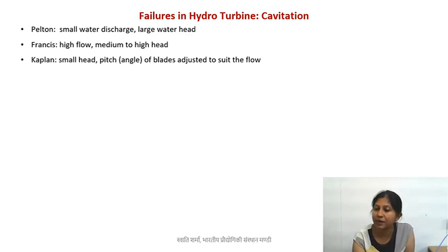The fluid is completely different. Not just that the fluid is different, one more thing is that the wind velocities can be very different at different time points. You know, sometimes you can have very turbulent winds, sometimes you can have no winds at all. But in the case of hydro turbine, you're pretty much controlling the flow rate of water. So that is one difference. Another difference is that in the water you will have dust, you will even have fish or small animals which will not be there in your wind turbine. That's not a problem there.